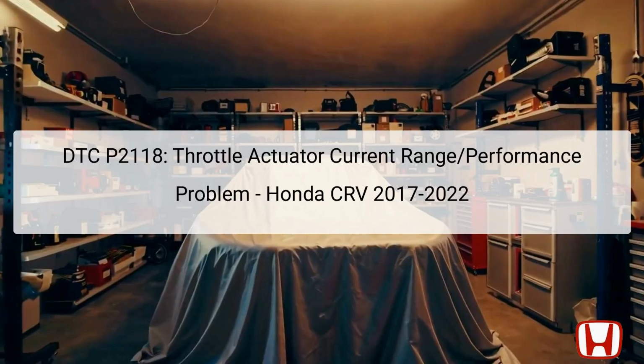DTC P2118 indicates a throttle actuator current range or performance problem in the Honda CRV model years 2017 to 2022. The throttle actuator plays a crucial role in managing the air intake of the engine by adjusting the throttle plate's position based on input from the accelerator pedal. It is typically located on the throttle body, found in the intake manifold, just after the air filter.